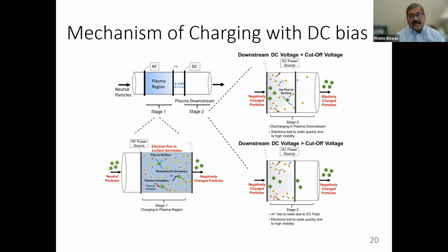Right. So that, of course, is challenging. This is where I always try to look. One has to even collaborate, because there are so many practical aspects in these systems, and it's not as clean and nicely controlled as in a laboratory. But in terms of doing this, it would definitely go upstream of the ESP system, right? So design it in a manner where the high concentration particulate stream could interact with the plasma zone, but you want to control the design of the plasma system. Now, plasma systems are being scaled up. In some sense, the corona is also like a plasma system. So there could be advantages of integration, but I won't go there.